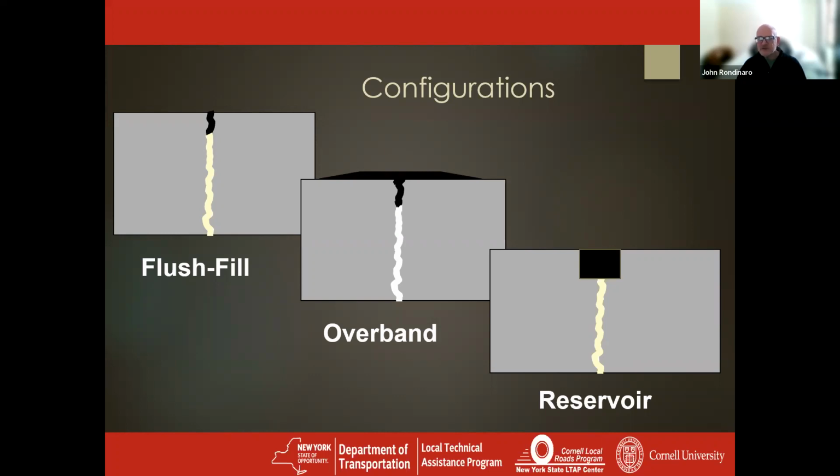And now, especially in terms of moving cracks, at least from the DOT perspective, we strongly recommend you use the reservoir. You route or saw in a channel, and that gives you a real nice amount of surface area for that highly engineered material to bond to.